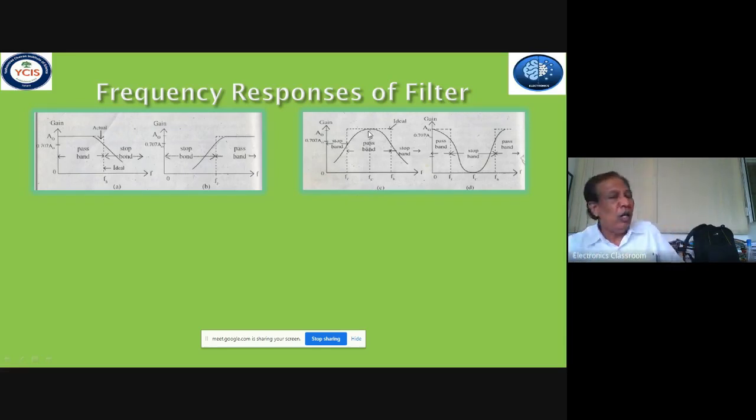आता एखाद्या असं म्हणू शकतो की why the gain is maximum. हा रिस्पॉन्स कसा दिसतो तुम्हाला, फ्रिक्वेन्सी वाढले की काय होतं, गेन वाढत जातोय, म्हणजे करंट वाढतोय, पॉवर वाढते. At one frequency the power is maximum, current is maximum, okay, and beyond that frequency, as we go on increasing it, again the current will decrease. What does this mean? Means at this frequency the circuit will behave as a resistive one. There is less opposition. Due to this maximum current will be flowing in the circuit, there is maximum power, and due to this maximum gain is observed, so that at frequency f equal to f0 the gain is maximum, current is maximum, power is maximum.